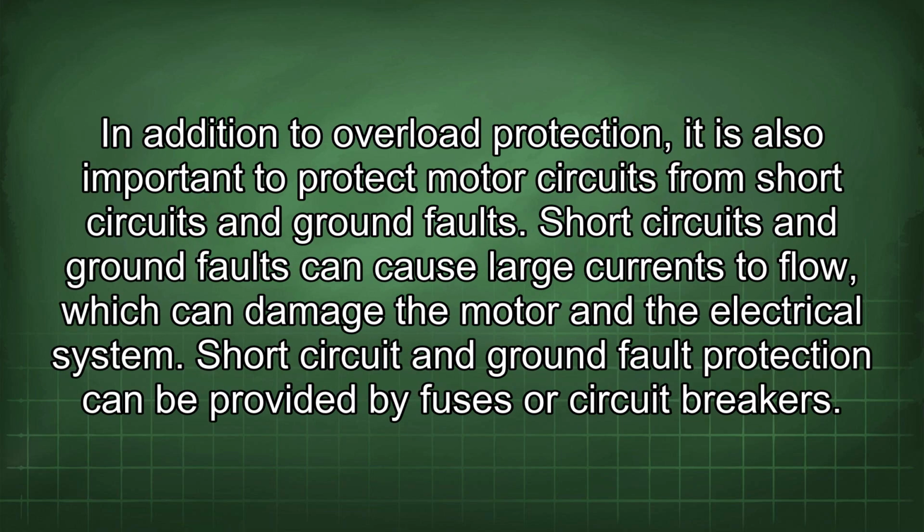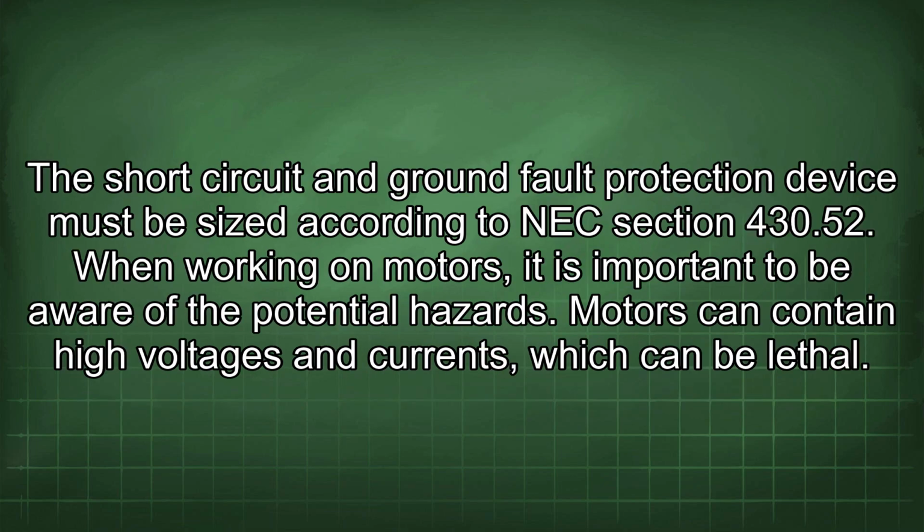In addition to overload protection, it is also important to protect motor circuits from short circuits and ground faults. Short circuits and ground faults can cause large currents to flow, which can damage the motor and the electrical system. Short circuit and ground fault protection can be provided by fuses or circuit breakers. This protection device must be sized according to NEC Section 430.52.